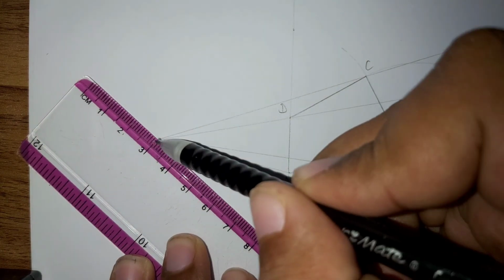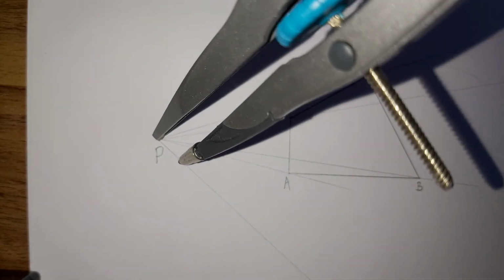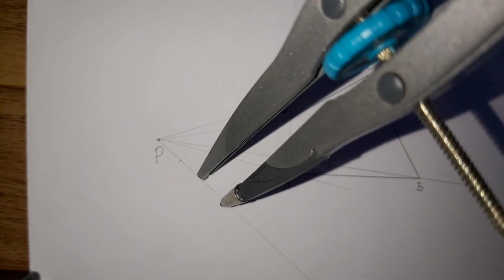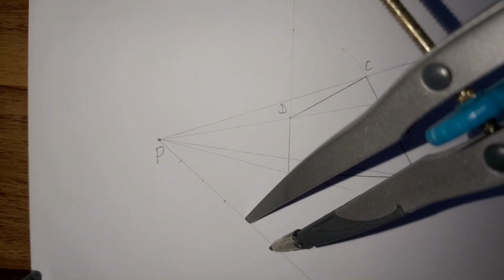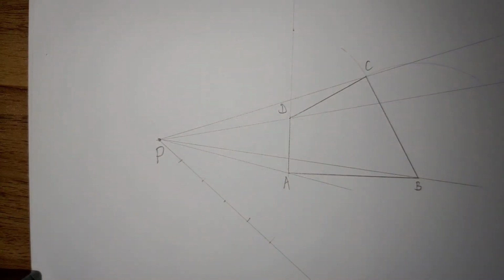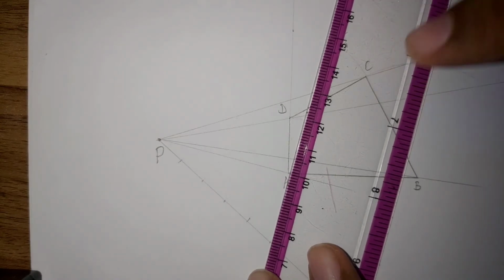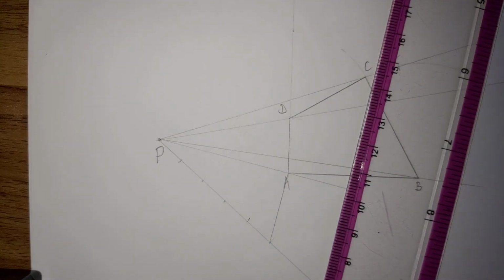Now, the next step here would be to divide PA into 5 parts, since the ratio being used for this construction is 3 to 5. So the last number, which is 5, is going to be used as the number for dividing the line PA. So if the ratio was something different, like 3 to 6, then 6 would be used instead. And dividing the line should also be something that I should not be showing you, since it's something that you did in Form 1 and Form 2. But regardless, it's being shown to you here.